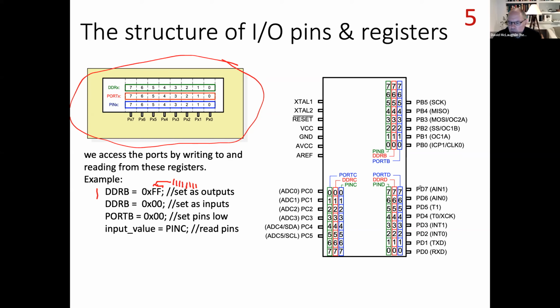So what that command would do is it would take all of these and configure them as output pins. So you could use those to turn on and off LEDs, or you could use those to make noise from a little piezo speaker, turn on a coffee pot, launch a rocket, right? Whatever you wanted to do with those pins. This line here, I'm setting those all to 0s instead of 1s. So if I set the data direction register pins to all 0, we're configuring them all as input pins instead. On the next slide, I'm going to show you the hardware that actually causes this to happen.